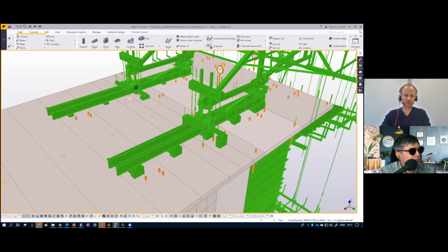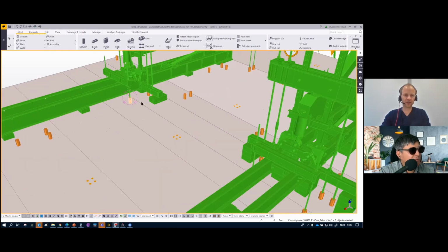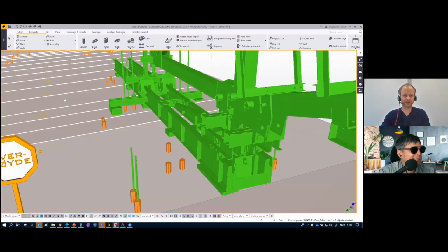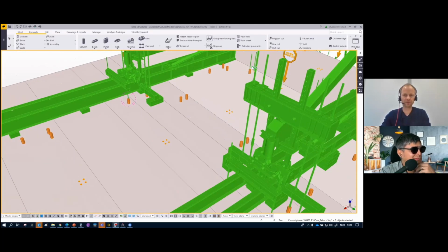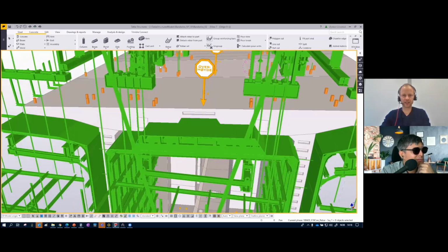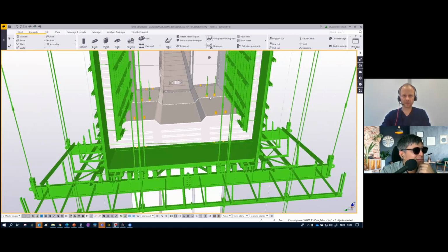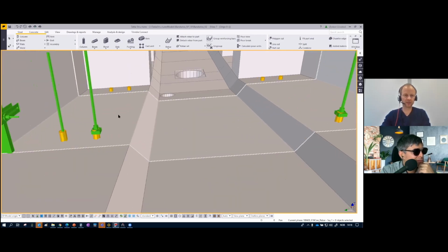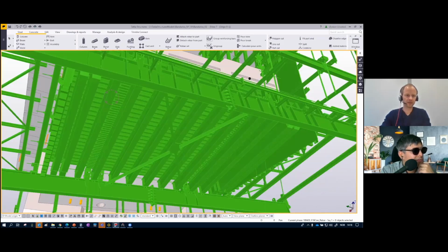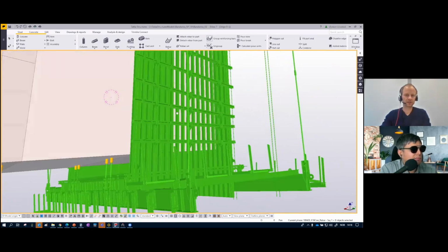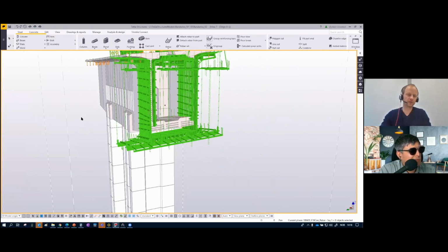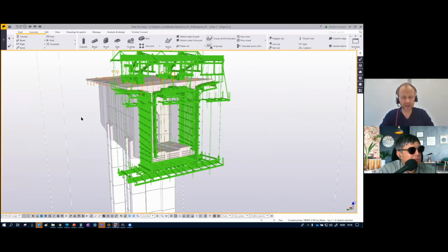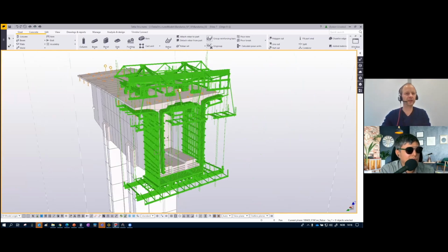Because it would be quite devastating if we had to start drilling new holes here. And here we see they fit perfectly at all the stages where I need them to fit. And if we go down here on the lower end, we also see that we hit the holes that we anticipate. So this is the beauty of the BIM design and 3D design. We feel we have very good control over things that would be very hard to do in 2D.